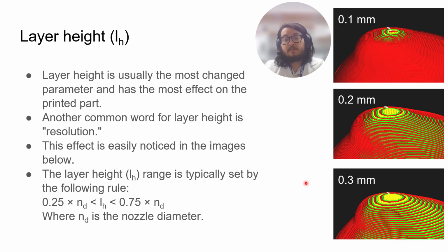Those slices definitely do look like those topographical curves that we see. So having these thick slices, as 0.3 millimeters is typically considered thick, you can have your print done pretty quickly, with this rough look to it.